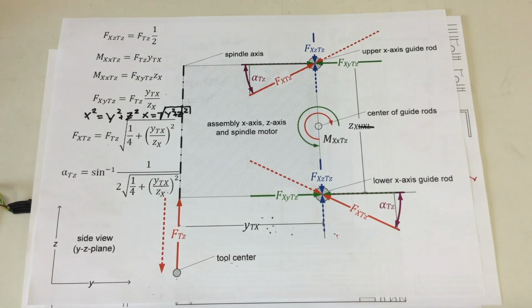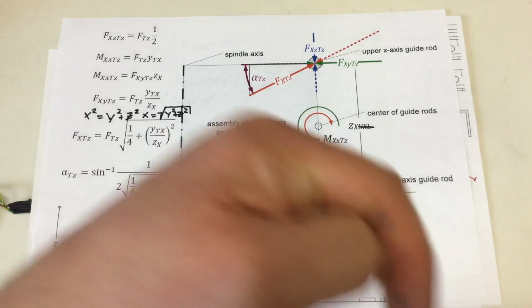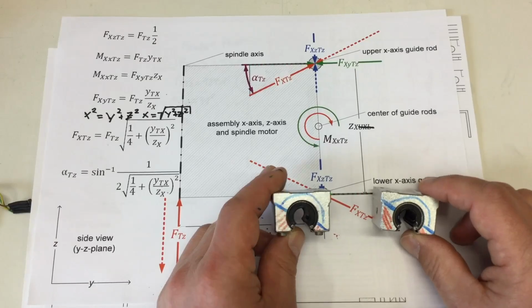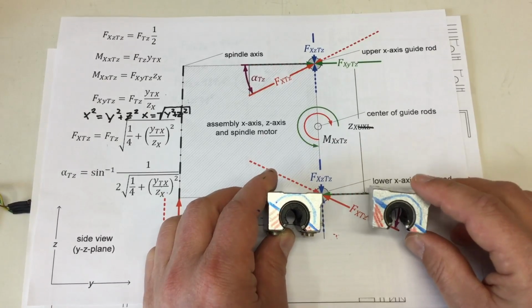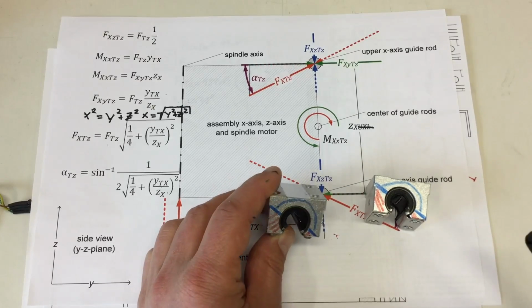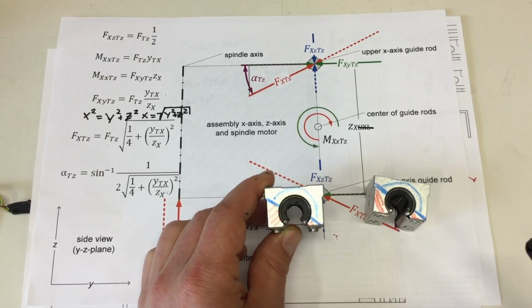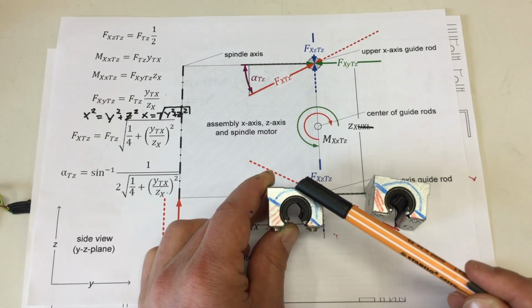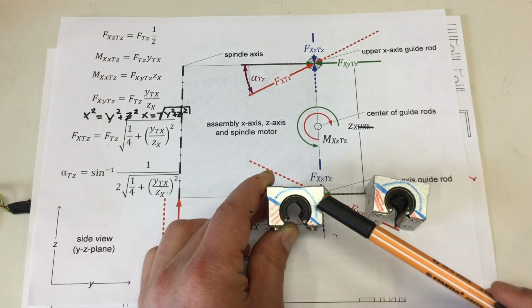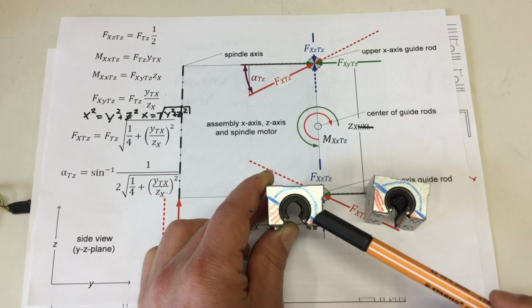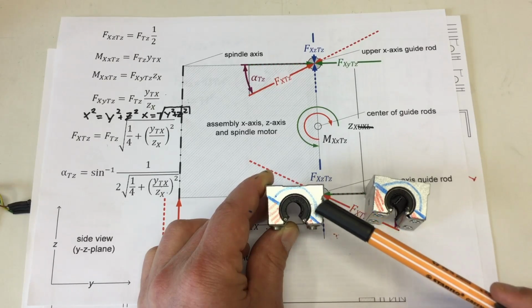And if I take now, again, in the video, my not very trusty SBR 10UU linear bearings, they have the oddity, at least I haven't looked at only a single bearing so far, that they can only take forces within 180 degrees, and they are not able to take any forces outside that area.